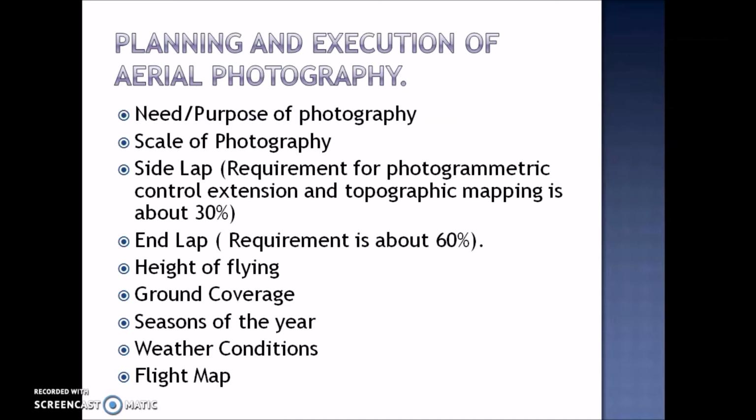If you are using a scale of 1:50, the map looks a little different, right? So we have to consider that parameter as well. If you are planning aerial photography, the scale of photography has to be considered based on the required scale of your map. That means whether we want a 1 meter precise length or a 1 kilometer precise length, that matters.